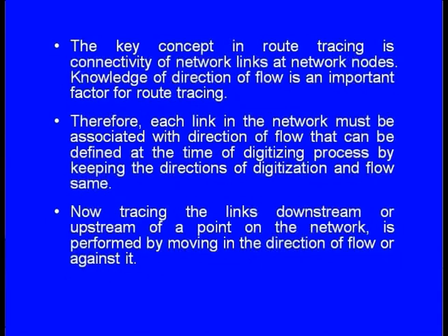The key concept in route tracing is the connectivity of network links at network nodes. Knowledge of the direction of flow is an important factor for route tracing. Therefore, each link in the network must be associated with a direction of flow that can be defined at the time of the digitization process by keeping the directions of digitization and flow the same.